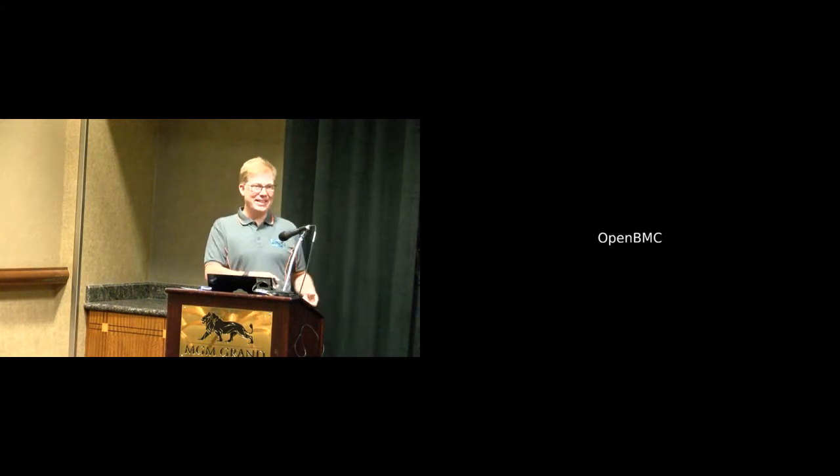If you go look at the AC922, there's a card with a BMC that comes out. So it's literally one of these on a desk with alligator clips into the power supply and a couple of other things off there, and you've got the BMC running on that. And then of course you could twiddle the right GPIOs to see whether the thing was booting and get all the initial bring-up done, because once we got actual Power 9 silicon, the BMC has to be able to turn the computer on or we can't do any development. And so that was when things started there.